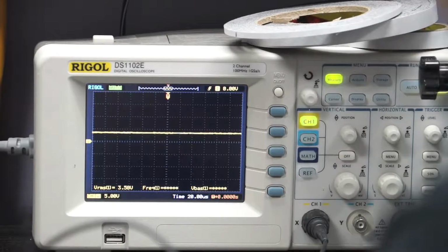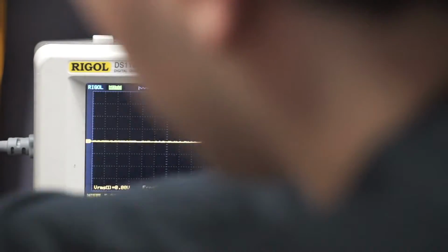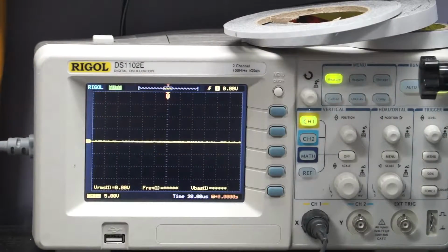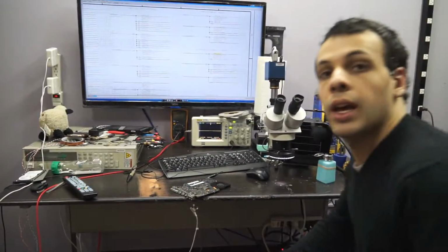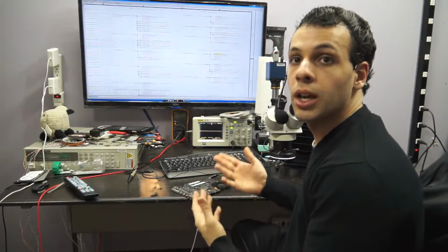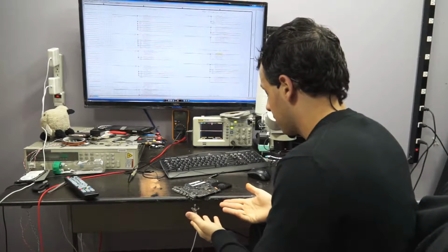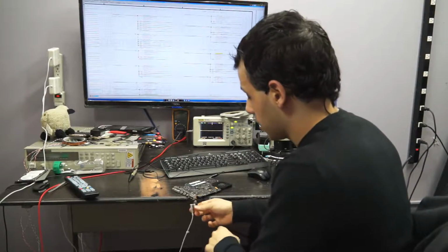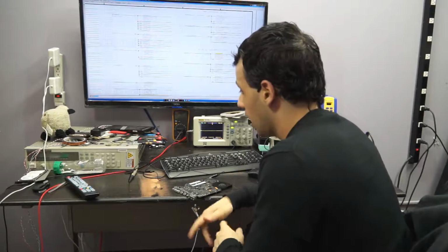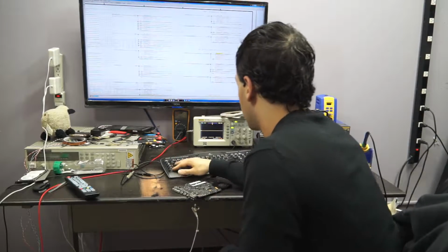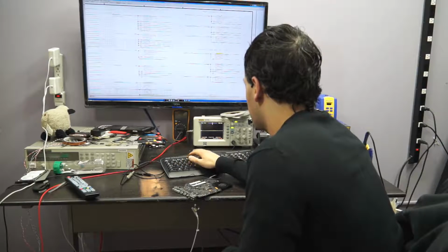At this point, I'm fairly satisfied that my power rails are present, and I'm ready to start considering other issues in the troubleshooting process. So one of the first issues that I want to troubleshoot is, why don't I have a green light? I should have a green light on this machine. I should have a green light because my power rails are present. So if PP3V42 weren't present, which helps power the one-wire circuit, I would understand why I don't have a green light. So let's go over one of the circuits that I've talked about many times.